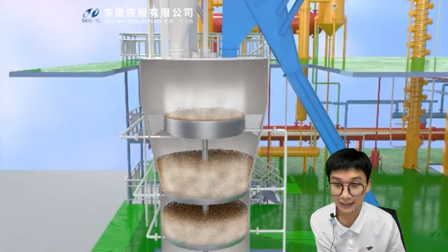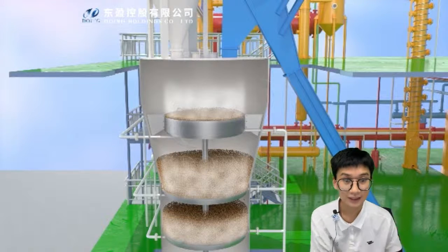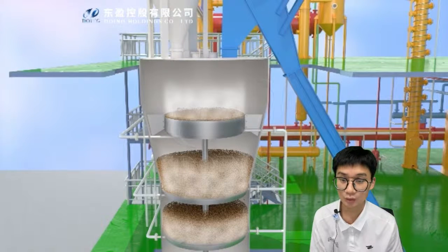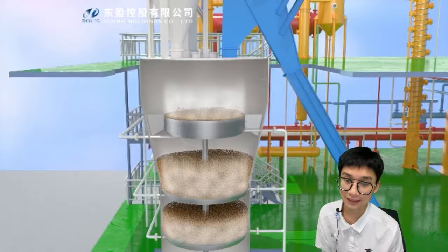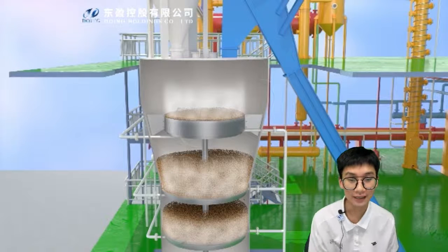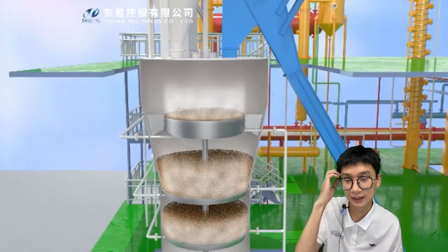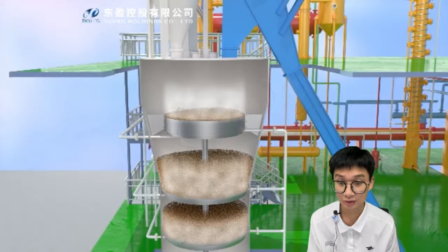As for the second, the desolventizing layer is also known as the self-steaming layer. It is normally layers 3 to 4. The main function is to bake the meal and remove the solvent from the meal. The meal is heated by indirect steam in the bottom interlayer and a mixture of gas passing through the meal. The third one is the direct steaming layer, also known as the baked meal layer or high material layer. The solvent in the meal is stripped by direct steam.